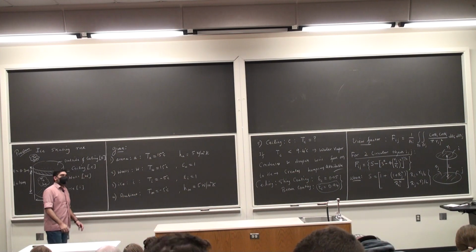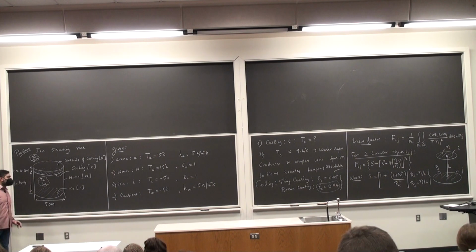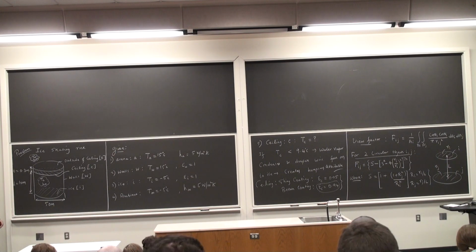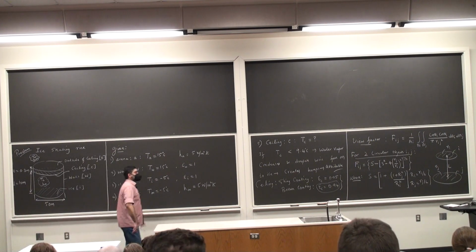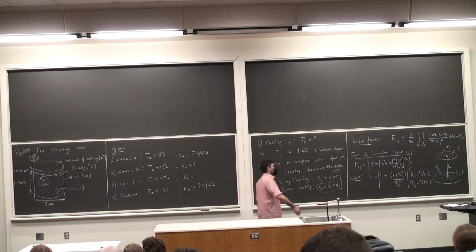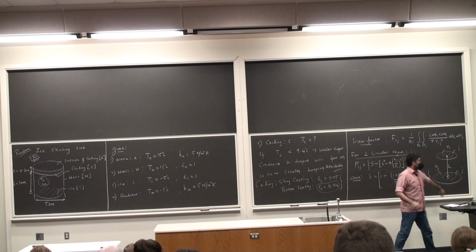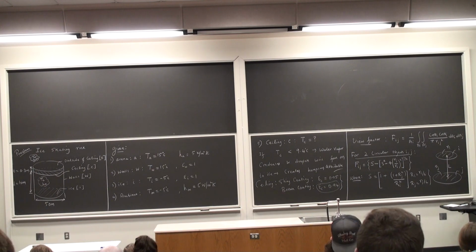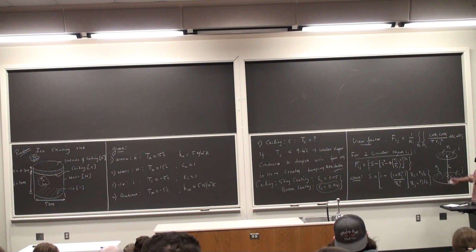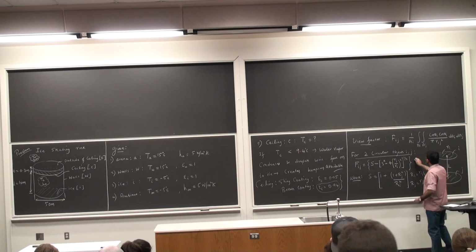So this is unlike the other problems we solved where we were able to discern the view factor without going through any extensive calculations. In this problem you have to make use of the given formula, and this can be given for different types of surfaces. The top could be a circular cross section, the bottom could be a triangle. The view factor would change. Likewise it would change depending on the nature of the surfaces. So this is a geometric measure.